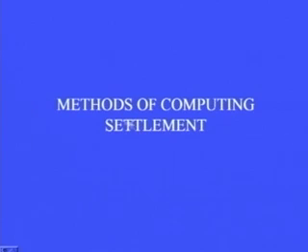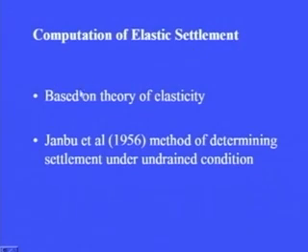Now, in order to determine the settlement, various methods are available. So, we are going to discuss now the methods for computing settlement. Computation of elastic settlement: this elastic settlement can be determined based on the theory of elasticity or a procedure given by Janbu et al. for determining settlement under undrained condition.